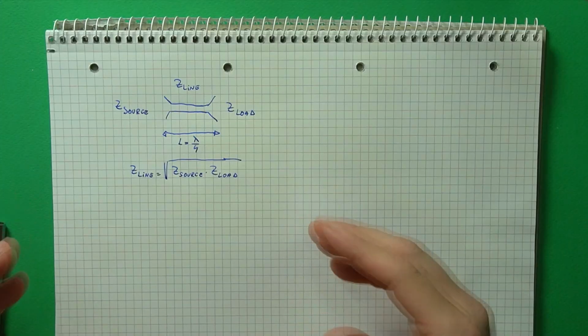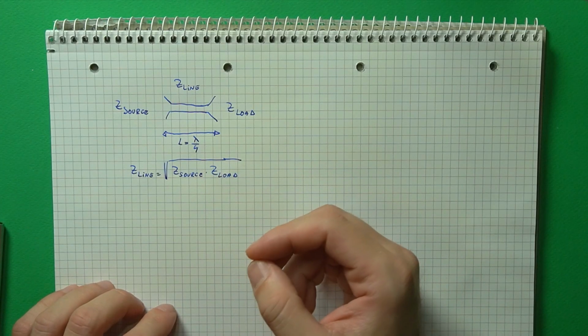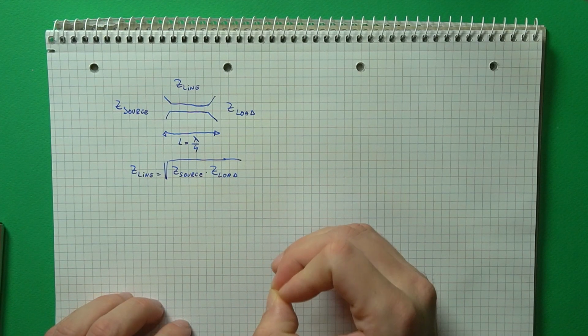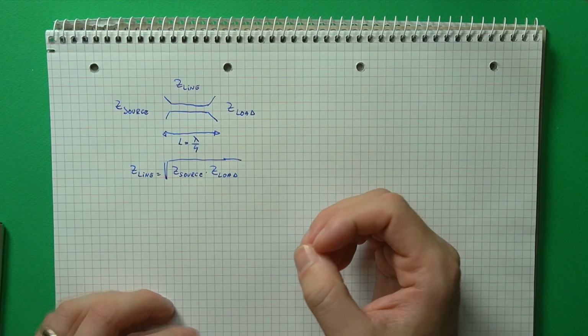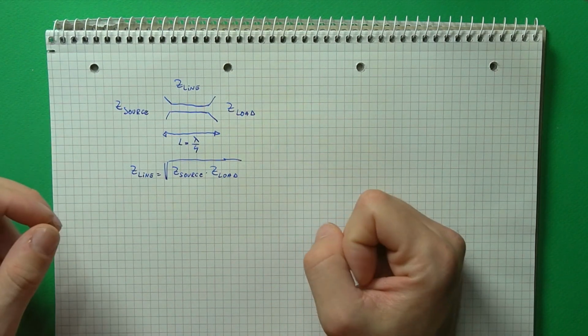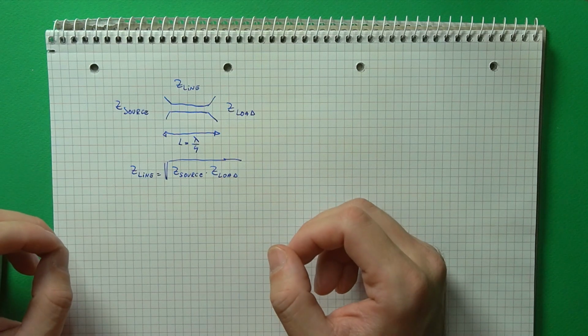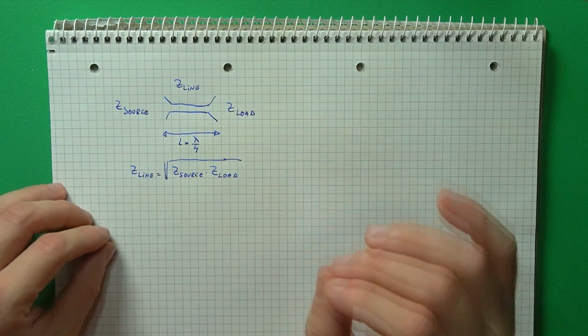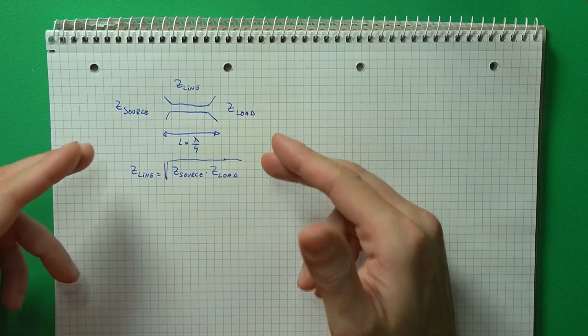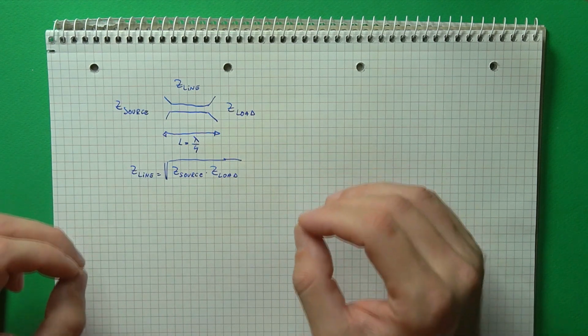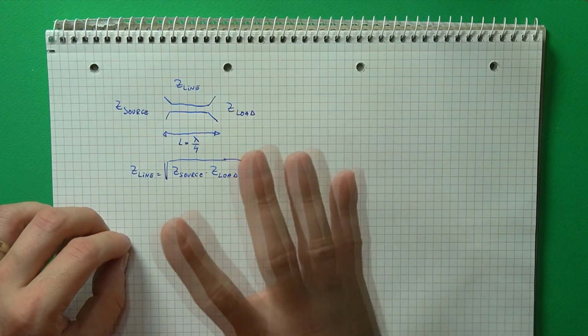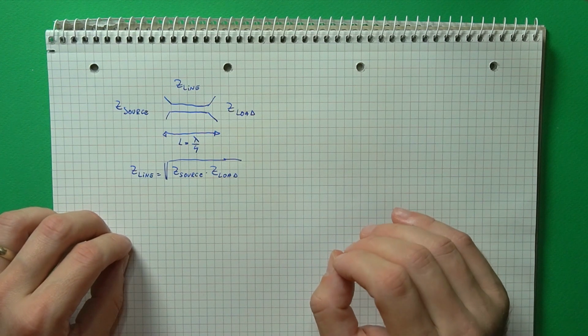So, it's like a transformer? Well, sort of. It transforms or inverts impedance. This is basically a transmission line that has a specific characteristic impedance, and it allows the match of a source and load impedance based on this equation. And this is valid at a frequency where the transmission line length is equal to a quarter of the signal's wavelength, and no other components are necessary.